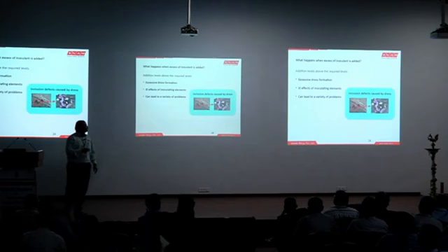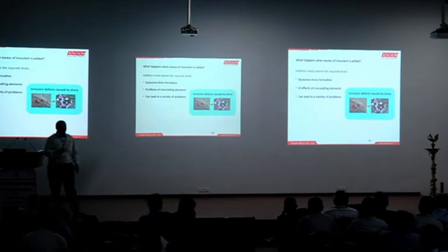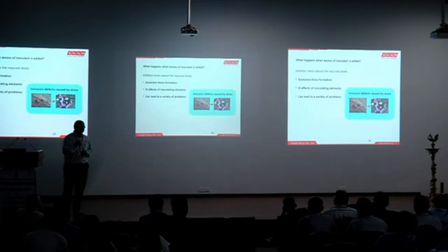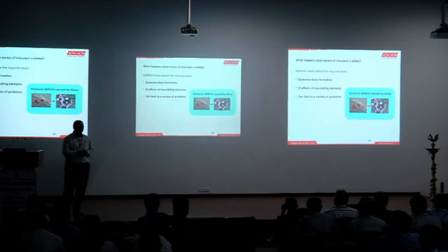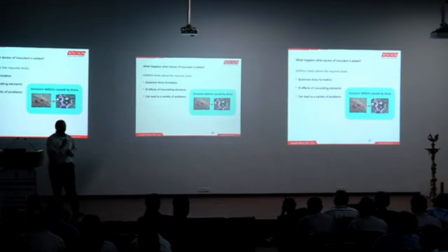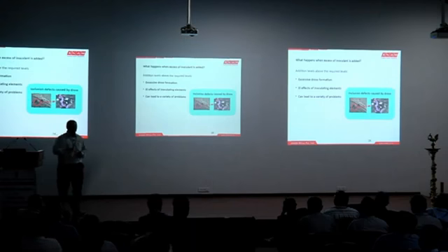So what happens when excess inoculant is added? The list of elements I had shown previously are strong oxidizing elements. By default, when you take liquid metal to a temperature close to 1600, oxygen influx happens and you start getting oxides in your liquid metal, nascent oxygen. When the temperature comes down, oxygen cannot stay, it starts reacting with elements present in the liquid metal and forms compounds. We can call it oxides, you can call it slag, or slag is made of silicates. Silicate is again an oxidized form of silicon. So ultimately it revolves around oxygen.